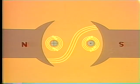Now, look at this end view of our conductor and the main magnetic field. Current flow goes into the conductor here at the cross or back of the arrow, and out here at the point of the arrow. Now, the smaller the load, the less current there is flowing through the conductor. That means there's a smaller field around the conductor, too. So the shift in the main field would be less. As the load gets heavier, more current flows through the conductor, and it has a bigger field around it. So it causes a greater shift in the main field.